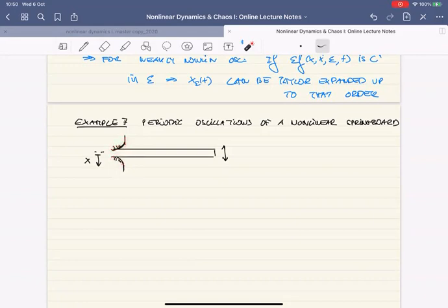This little arch here. So effectively, what you can imagine is that if I start displacing this beam and it starts touching this arch, this radius, then the effective length of the beam which is freely oscillating has become shorter. If it has become shorter, that means it's effectively a stiffer beam, in both directions.